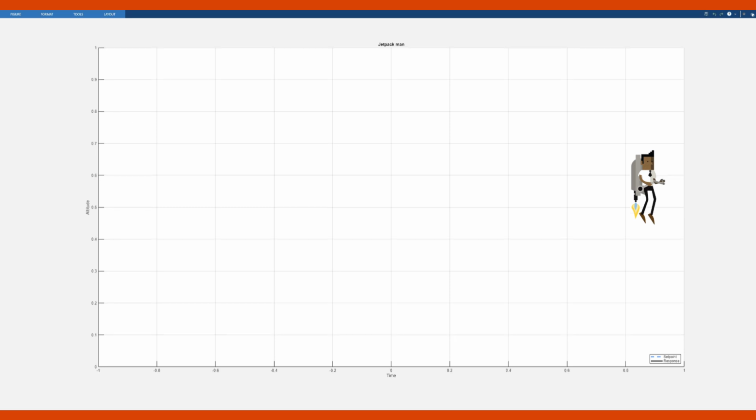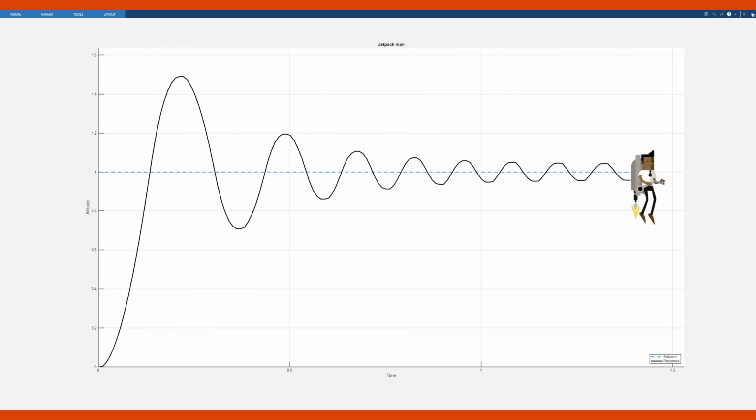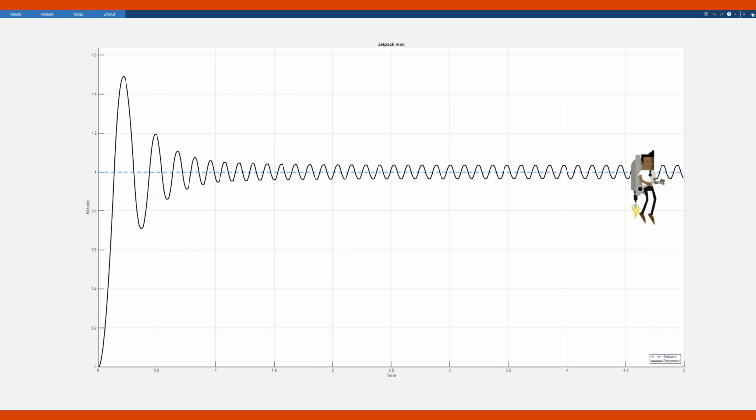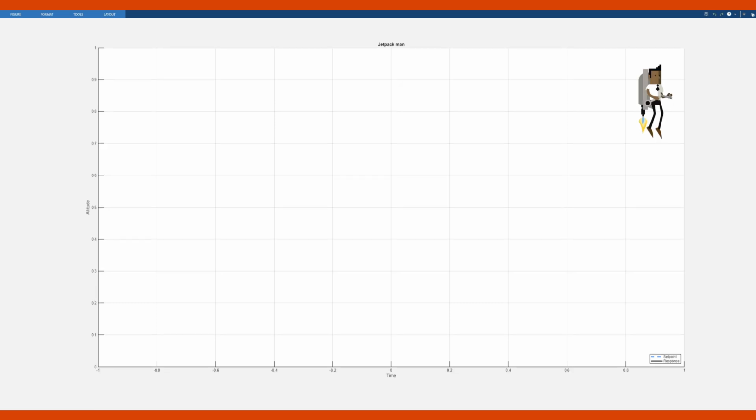We're going to switch Jimmy to proportional derivative, or PD control. Jimmy's path using PD control initially looks pretty similar to what we saw from bang bang control. The difference is, with PD control, we can use damping to control Jimmy's path. You can think of damping like a shock absorber that slows our rate of ascent to help keep us on target. Let's see what it looks like with some damping.